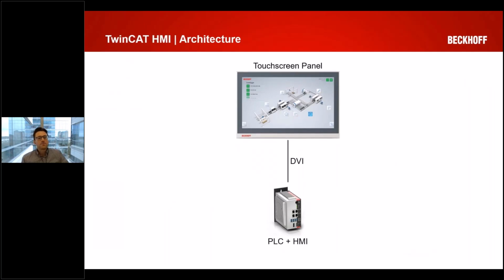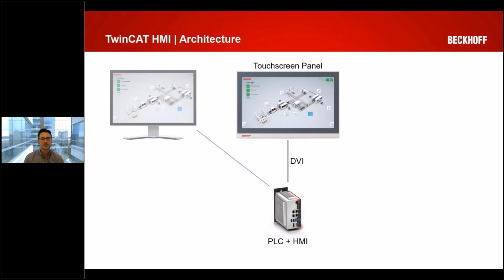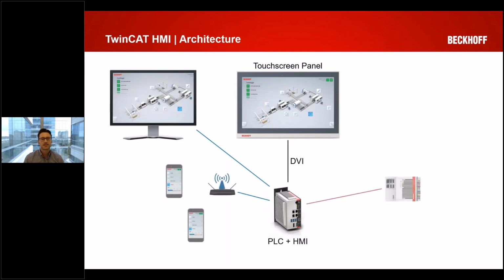All right, now keep in mind, just because it can do all of that doesn't mean it has to. The simplest configurations are still easily achievable and cost-effective on this platform as well. So for instance, running everything on a single controller and just using the video output from that device and a dumb touchscreen monitor as your HMI terminal. The important part to understand is that regardless of where you start, you can always scale the requirements of your application, thanks again to that architecture.